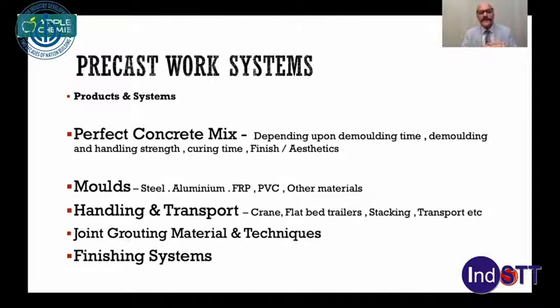And the third aspect when you design concrete is what finish you want after the concrete comes out of the mold. That is the aesthetics and the finish. So you can have various molds, and on the molds you can have many designs, inlays, or texturing, so that the final product has that look. Coming to the molds, where the precast concrete is put in, you can have molds in steel, aluminum, FRP, PVC, and many other materials also.